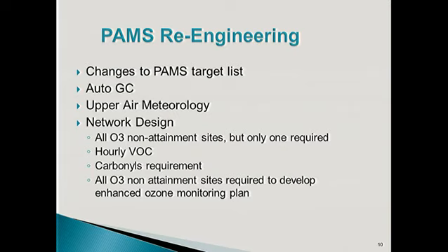But really, modelers have been asking for hourly data to match our normal air monitoring station data. So to push some of the limits of getting VOC data at the hourly rate, they're looking at auto GCs to be implemented at the stations to be able to match the hourly rate that the other instruments are producing the data. And then lastly, the carbonyls method, there's a lot of issues surrounding that, but with the idea that the carbonyl components are some of the highest ozone-producing compounds, they couldn't give it up, but we're looking into better methods on how to conduct that particular measurement.